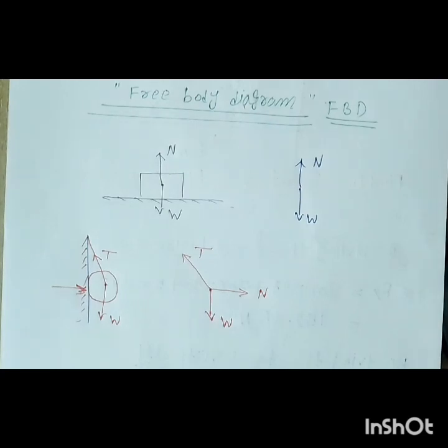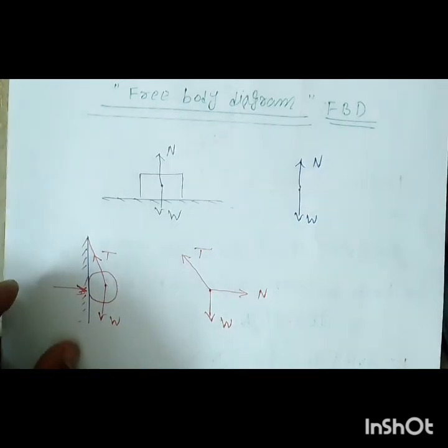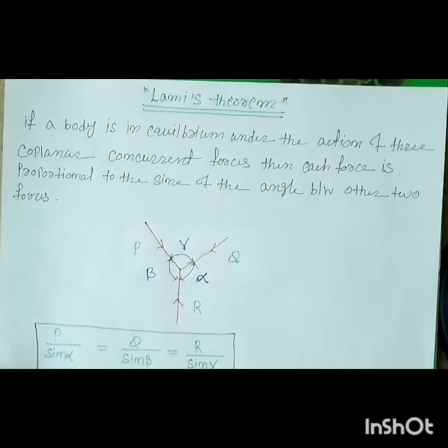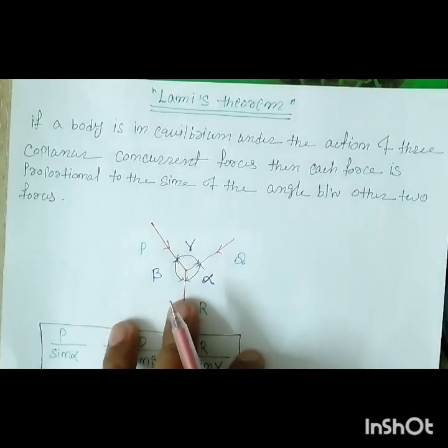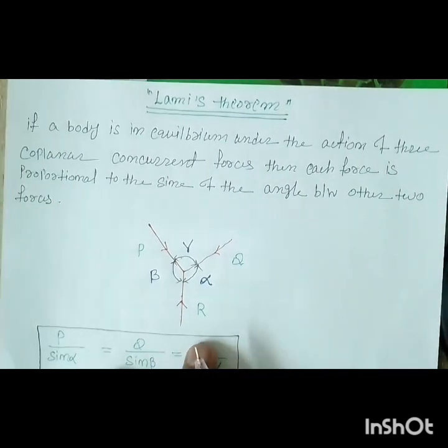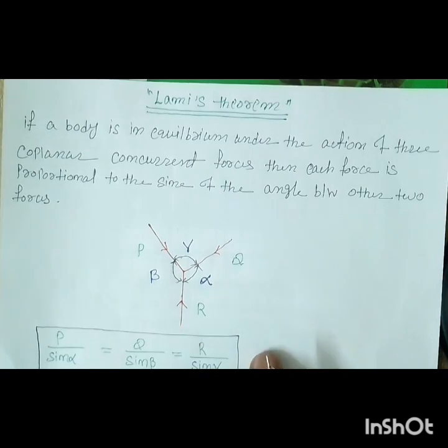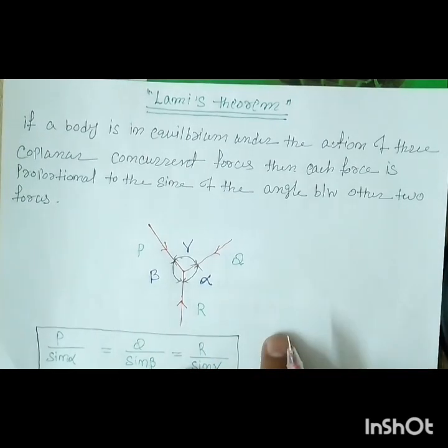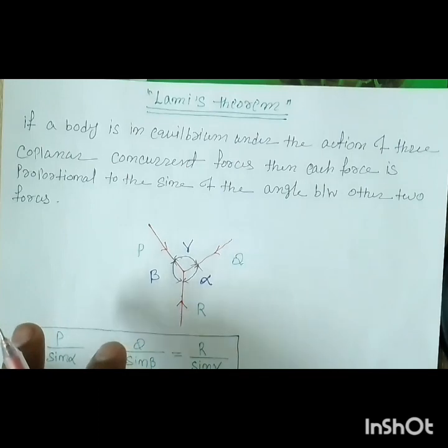It's very simple. Now we'll move to the next topic, Lami's theorem. So what is Lami's theorem? First of all, try to understand that Lami's theorem is applicable only when we have three forces, and these three forces are coplanar and concurrent. If you have three coplanar and concurrent forces in equilibrium, then each force is proportional to the sine of the angle between the other two forces.